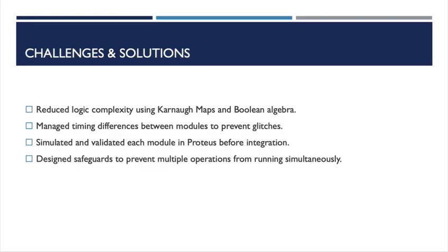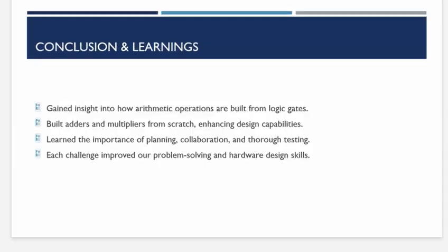The second challenge was ensuring consistency and accuracy across modules. Since each arithmetic operation has different internal logic and timing, integrating them without introducing glitches was really difficult. We solved this by thoroughly testing each module in isolation in Proteus before integration. Additionally, we designed control logic to prevent multiple operations from activating simultaneously.